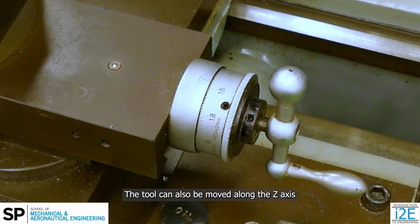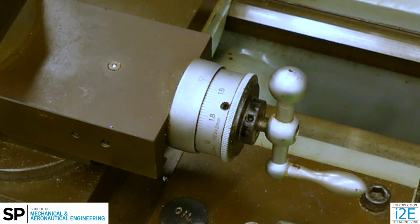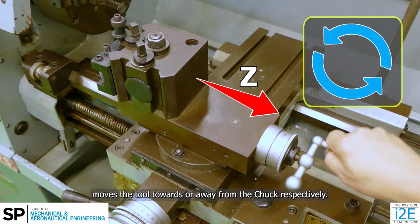The tool can also be moved along the Z-axis when using the compound slide handwheel. Rotating it clockwise or counterclockwise moves the tool towards or away from the chuck, respectively.